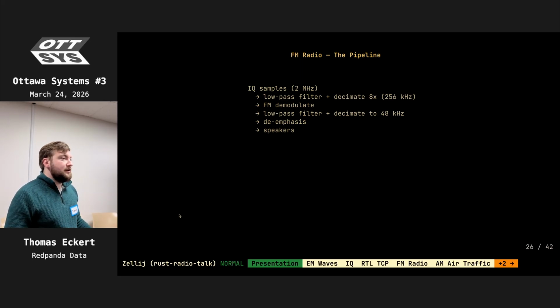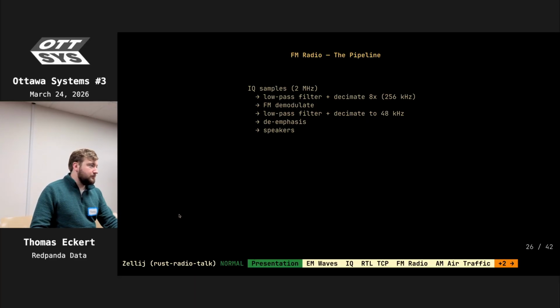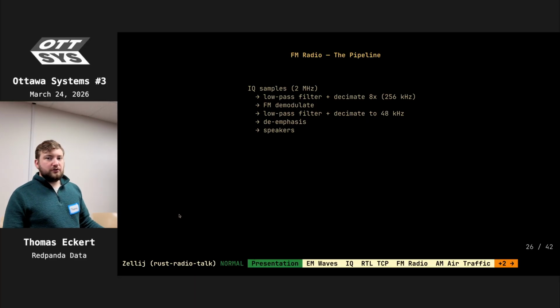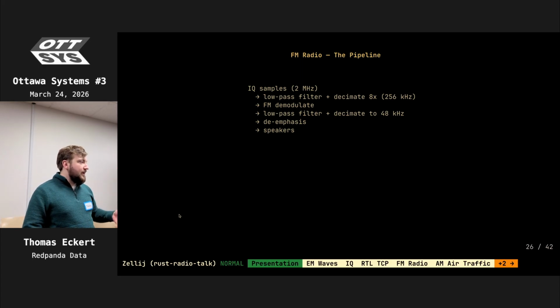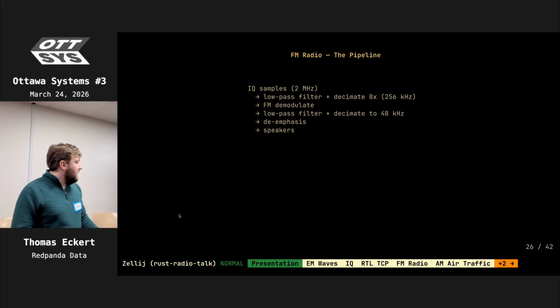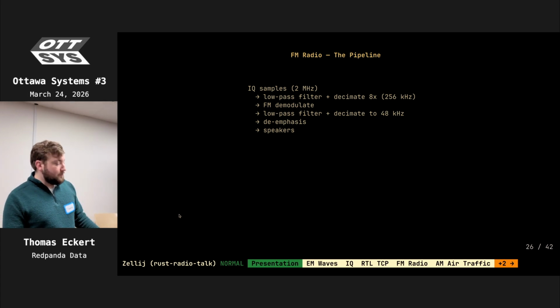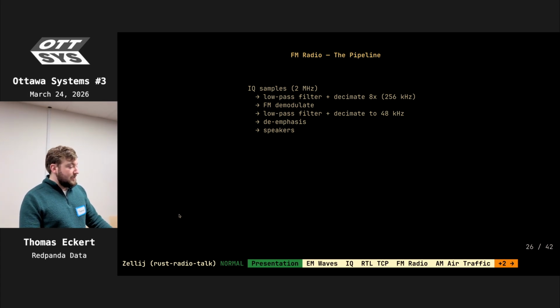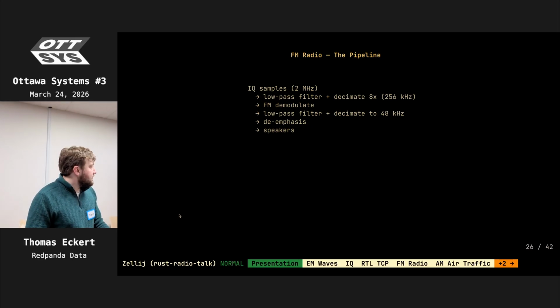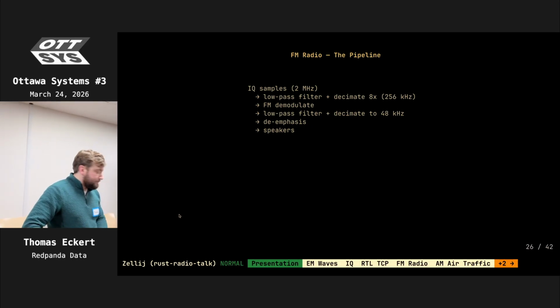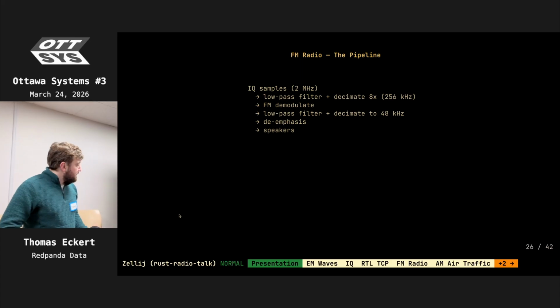Decimate just means decimate by 8x, take every 8th sample, right? There are certain limits to the quality of information that we're going to get and the quality of what we can hear. And then I do a demodulation, and then I do another low pass, and then I decimate even more, just because of the nature of the quality of what we can even hear from FM radio, and then do some de-emphasis, and then I put it out over the speakers.